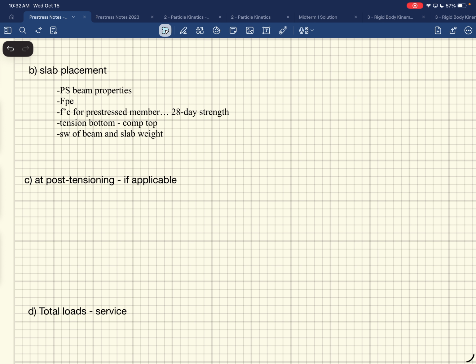Could be ducts. But typically ducts along the length, right? Or they could have those post-tension tendons stretched or included throughout. So then you cast the concrete, and then you let that concrete that you just placed come to strength, and then it's composite, and then you can post-tension it and then pop it back up. And you can see why you'd maybe want to do that, right?